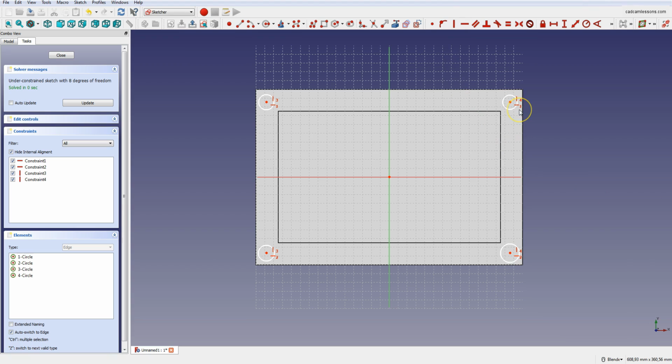Okay, the holes are already partially oriented with respect to each other, and now we have to dimension them relative to the edges of the model. Use the create an edge linked to an external geometry option to convert these 2 edges. Okay, and now let's add dimensions so that the hole centers are offset 12 mm from the edge.